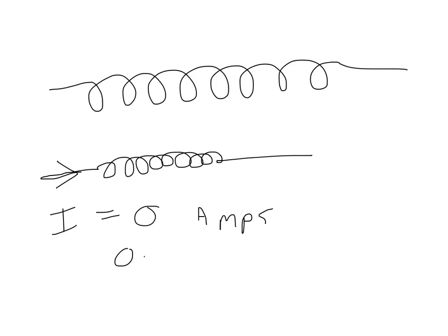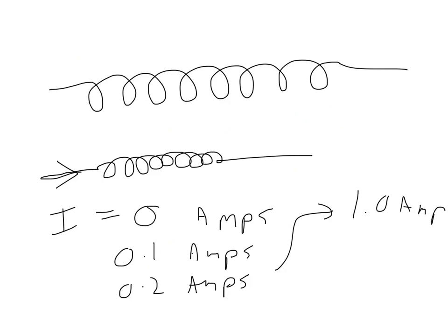You'll start at 0 amps, and you will ramp up. You go 0.1 amps, 0.2 amps. And if you have a power supply that can handle it, you'll go all the way up to 1 amp. Some of the power supplies only are able to get to about 1/2 of an amp. So I'll have you go as high as you can. If you can only go to 1/2 of an amp, you only get 5 or 6 data points for that. If you can get up to 1 whole amp, then you'll have 10 data points.